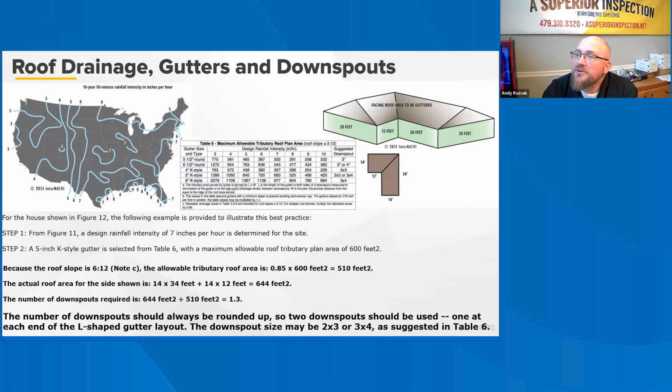While roof overhangs and porch roofs protect building walls from impinging rain, gutters serve to protect building walls and foundations from roof water runoff. Roof gutters, downspouts, and leaders or diverters form the initial components of a drainage system for the building and site. A proper design of gutters and downspouts for water shedding, steep slope roofs should be looked for during an inspection. Common problems with guttering are associated with the installation and maintenance.